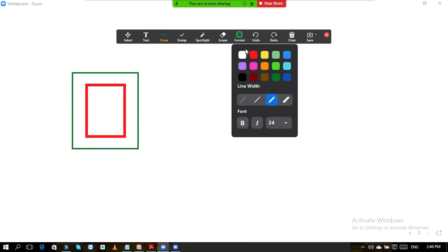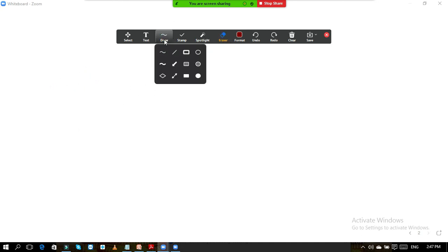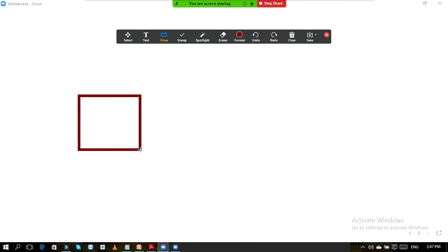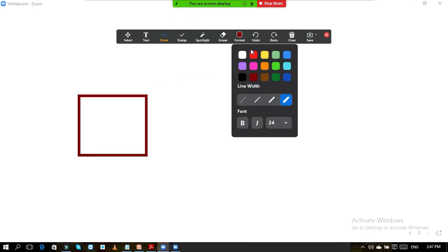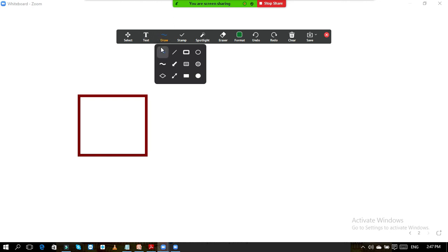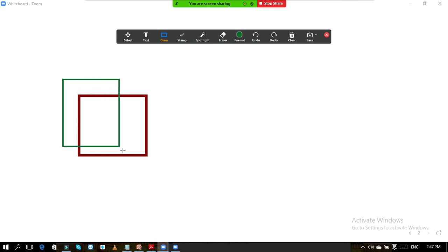Here, how many bars are there? 8 bars are provided. 500 by 500 means it is a square column, nearly a square column. So for more clarity, I will draw the neat diagram. First of all, again I will go for the stirrup. It should look like a square. Next, we will draw the column which is outside. So this is the cross section of the column.